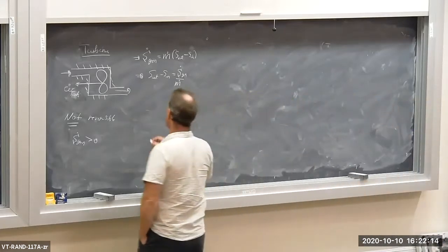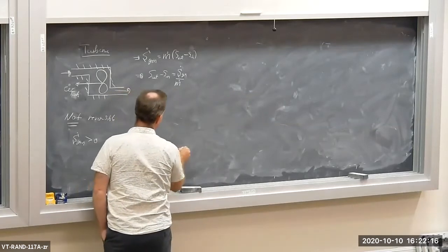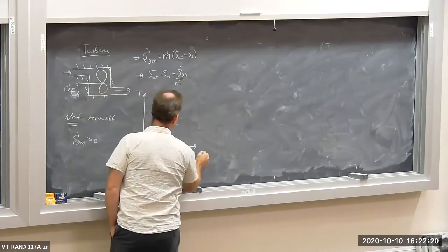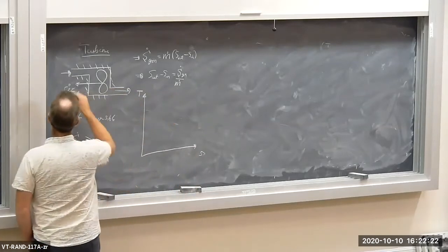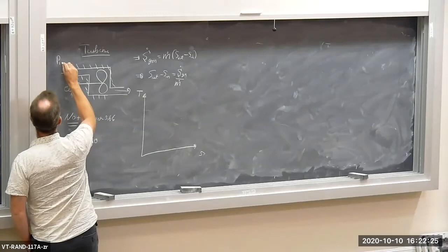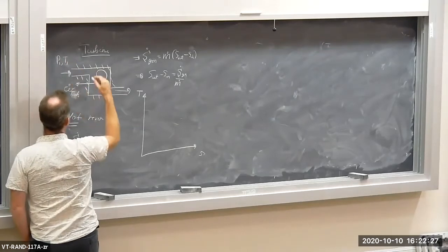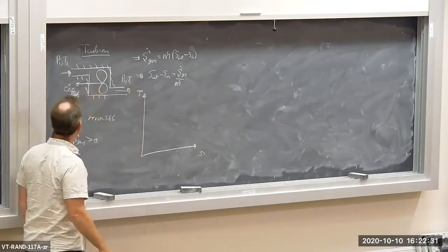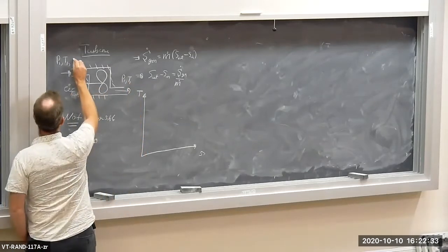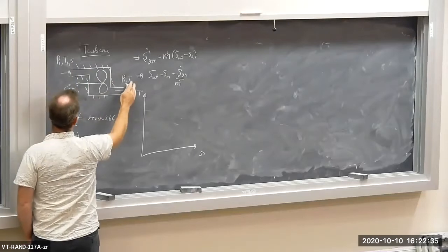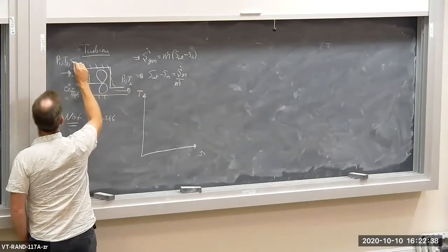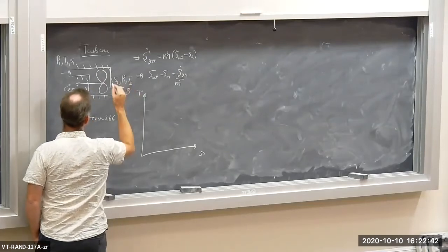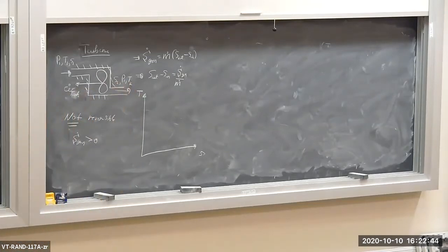So if I draw the TS diagram for this device here, let's say I've got an inlet pressure P1 and an inlet temperature T1. I have an outlet pressure P2 and an outlet temperature T2. Of course, I have specific entropy too. I have S1 and I have S2. Okay, so I have inlet and outlet properties.